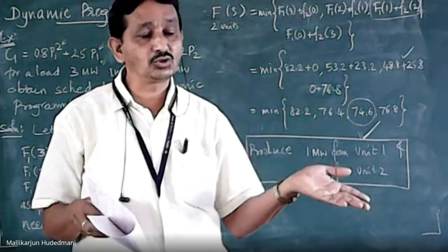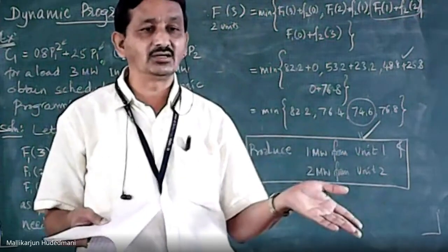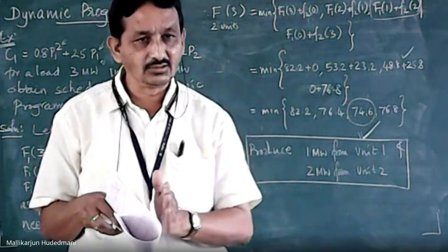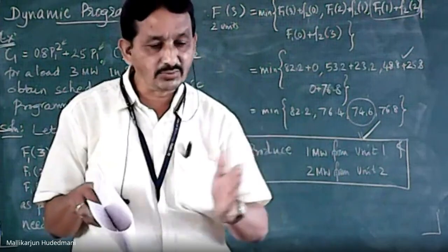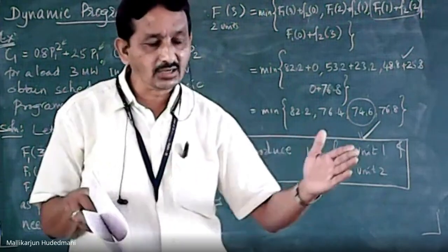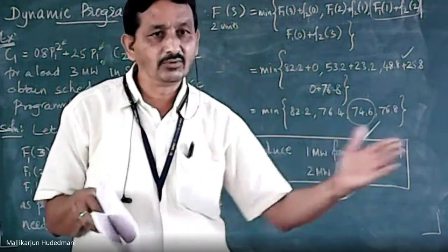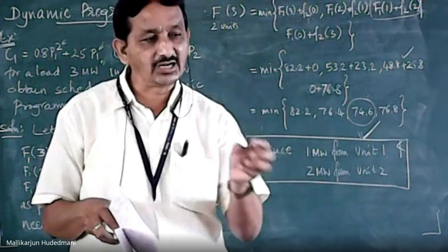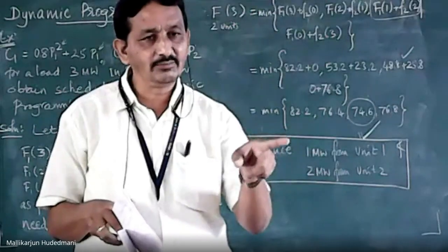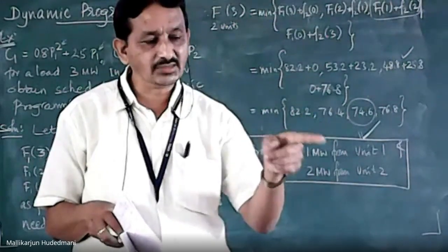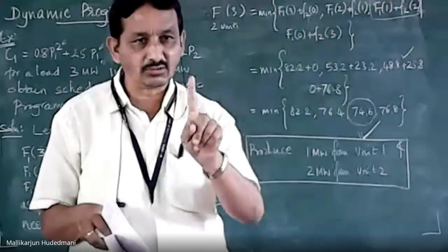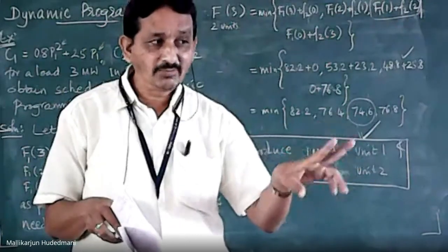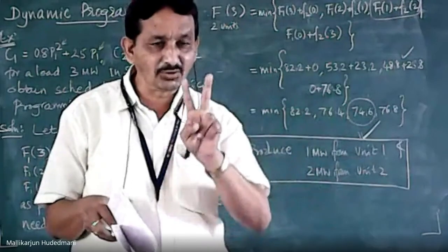Whenever you are supposed to combine all 4 generators to meet the demand, priority number 1 is the first attempt. Priority number 2 is combined with that. Priority number 3 is combined with that. Priority number 4 is combined with that. How many decisions did you take? Only 4. The first decision was identifying the best among the remaining. Among the 4, what is best? That is priority number 1. Decision number 1 has gone. And of the remaining 3, which one is best? Pick it and combine with the first. That is your priority number 2.